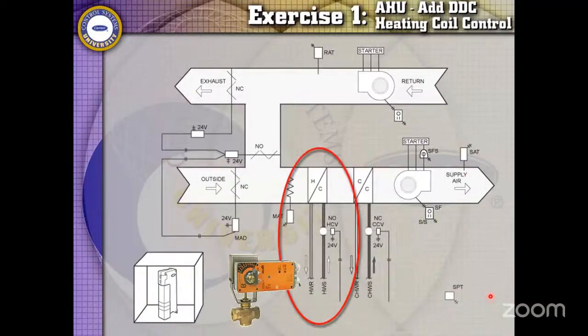We're going to have a hot water coil as well, right? Or it could be a gas heater or electric heater or something else. But in my case, it's a hot water coil. I'm going to modulate that based on the same exact supply temperature sensor I had. I'm only going to modulate it during morning warm-up. After morning warm-up, you don't get heat. I don't care about you anymore. I'm running cooling only. So it modulates during morning warm-up to maintain a specific discharge air temperature, typically like 90 degrees. And I use that to warm the space up initially in the morning. And once we're warmed up, it immediately shuts the hot water valve and then immediately starts opening the chilled water valve. There's no dead time in between.